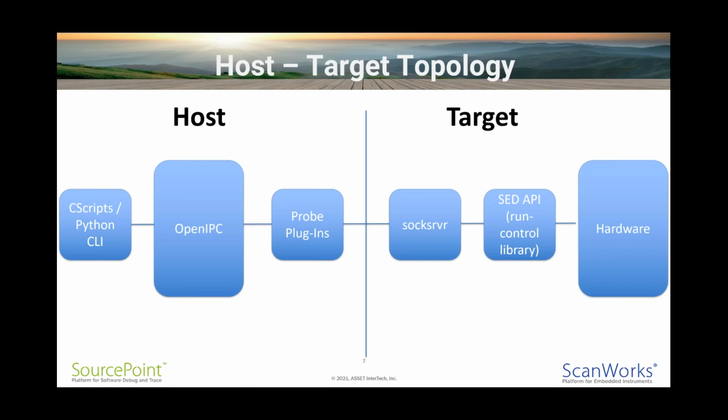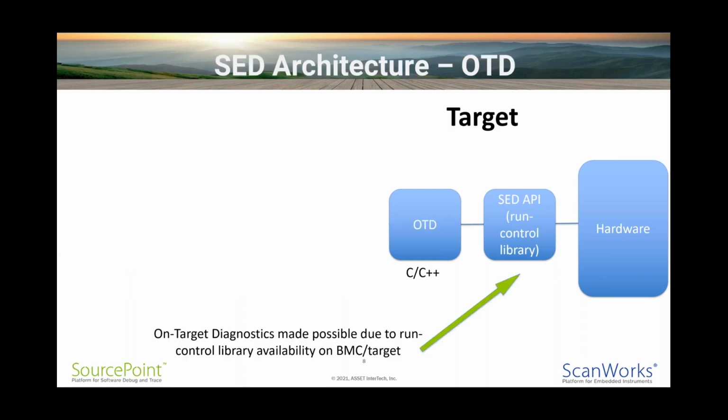The socket server is just taking commands from the host and funneling them down, invoking the API and executing the embedded ITP run control library, which in turn issues the needed JTAG scans and sideband signaling needed by the Intel hardware to perform run control. So this is the remote Intel CScripts approach.